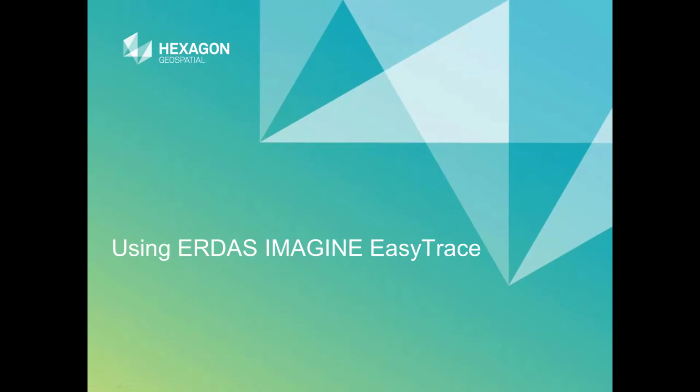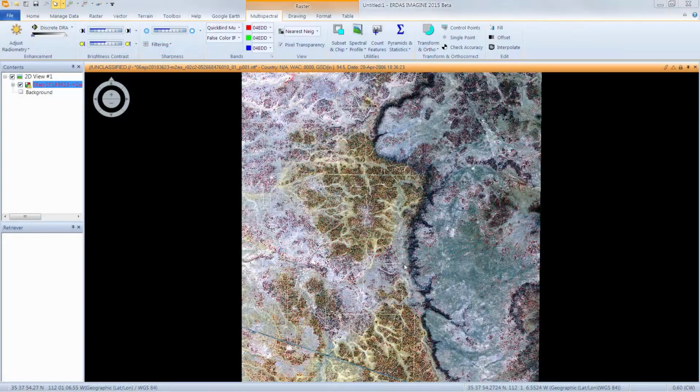In this module, we'll look at digitizing polygon vector features from satellite imagery using the Easytrace-assisted digitizing tools. I'm starting today with a multispectral image loaded in the ERDAS IMAGINE viewer. This image, a QuickBird 2 image provided by Digital Globe, is displayed using a false color infrared band combination to emphasize the difference between tracks and surrounding sparse vegetation.